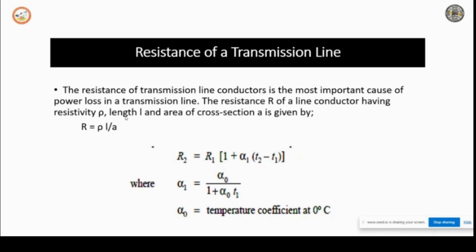The DC resistance computed from the above equation is actually greater for standard conductors, as spiraling of the strands makes them longer than the conductor itself. This increase in resistance is taken as 1% for 3 strand conductors and 2% for concentrically stranded conductors. Temperature is also one of the factors which will change the DC resistance of the metallic conductor, because you know the coefficient of thermal expansion. Now its variation with resistance will be there always.